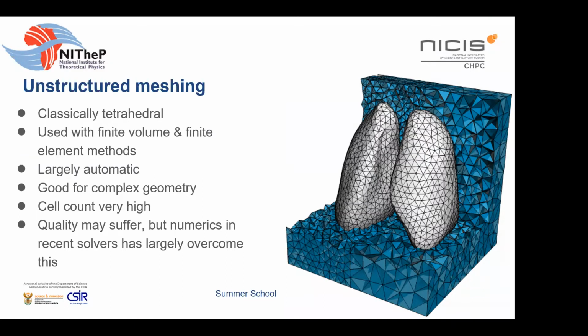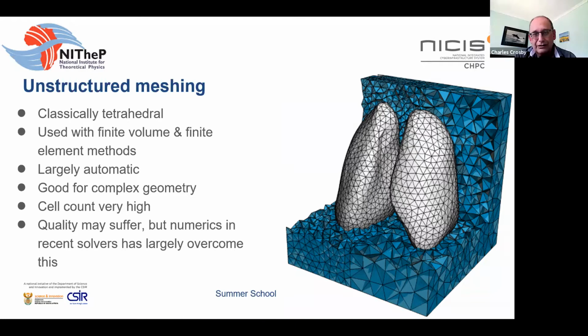You know, an object is designed for a certain purpose, and then you do the analysis to work out how well that works. You don't design it from the point of view of making it easy to analyze, although there's a certain attraction to doing that. For designing the mesh, you want to look at the geometry. The flow is generally going to follow the geometry. So if the mesh lines close to the body follow the contours of the body, then they are more or less going to follow the contours of the flow, the streamlines of the flow. But there'll be a bit more of that in the next slide.